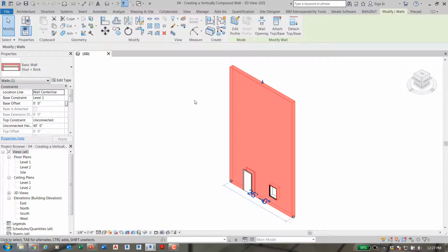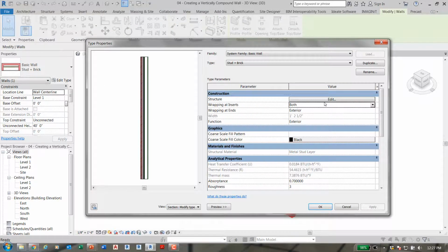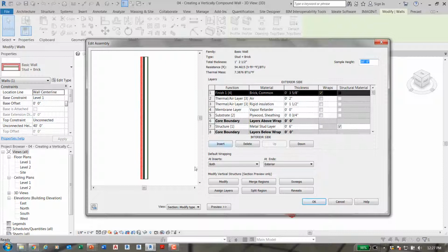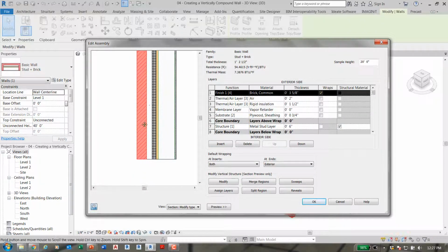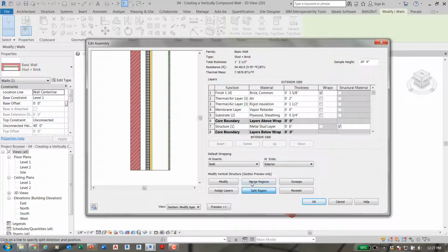Okay, so again, I'm going to go back to edit, and zoom a little closer. Okay, so I'm going to split it roughly right there. And what I want that to be is actually 2'6". And what I'm going to do is hit modify, hit the little split line. The dimension pops up for me to edit. I'm going to go 2.6.